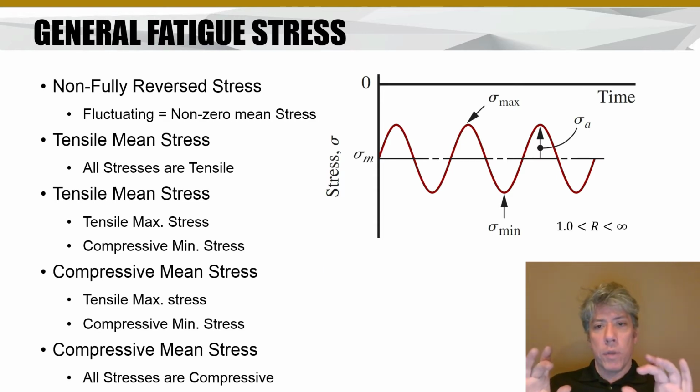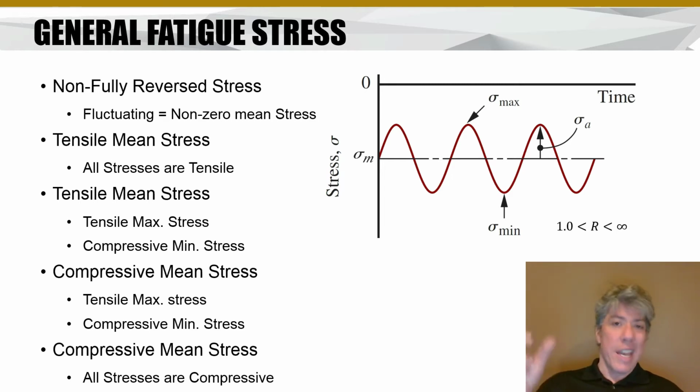And as we move this closer and closer to where sigma max is approaching 0, again, it's in the denominator, so that would approach positive infinity. It's going to be negative, but close to 0. So the minimum stress that's negative divided by a very small negative maximum stress will get you close to infinity. So there are the stress ratios for various types of fatigue loading or fluctuating stresses.